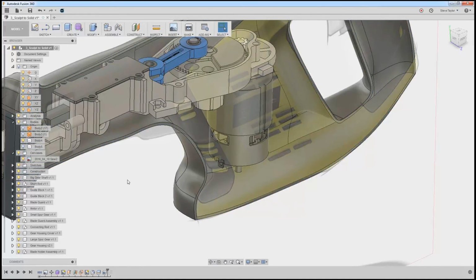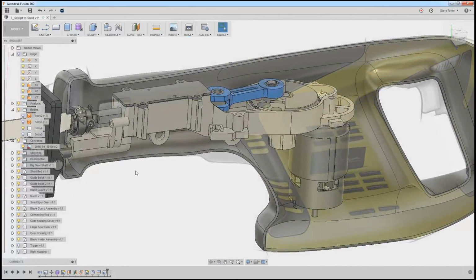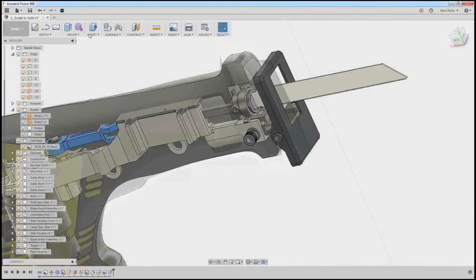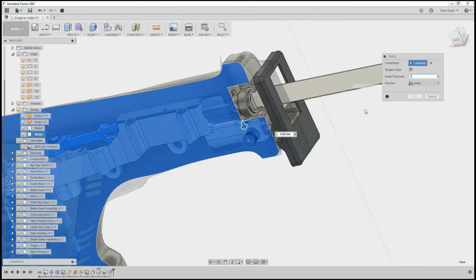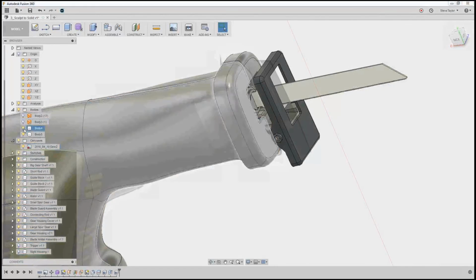That's looking a lot better, and you'll see that the fillet does follow that. You can see there that you can make mistakes, and you can very quickly with Fusion go in and rectify them and sort out what you've done. You haven't lost any details, and it's just a great tool for doing it. So may as well make it complete and shell this side as well. Modify shell like that, 2mm, press OK, and then we've got that complete. Excellent.